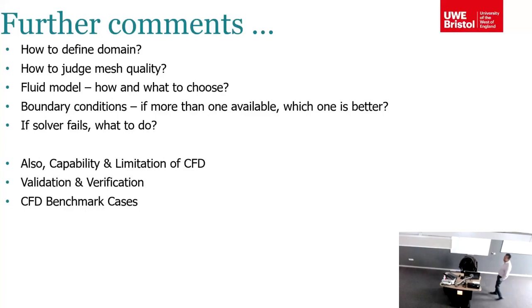And you need to know the limitations of the codes and the computers as well. So you can do a back of the envelope calculation for the size of the problem. If you have, say, 5 million grid nodes, will it fit your computer? That's a very simple problem. So start small.